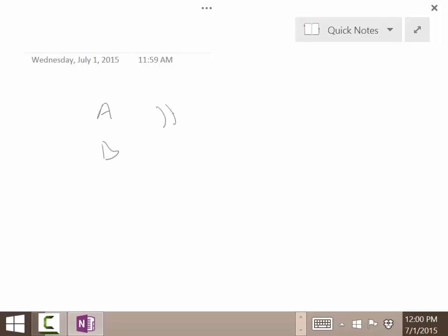If we go through a half adder, this is the symbol for the XOR. If we go into here, there's my sum out, and then we go through an AND gate right here, there's my carry out. That's a very simple adder. This will add that.